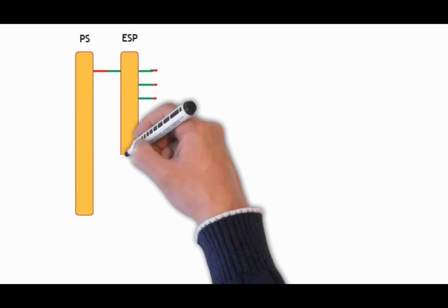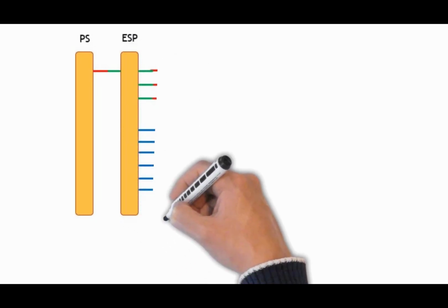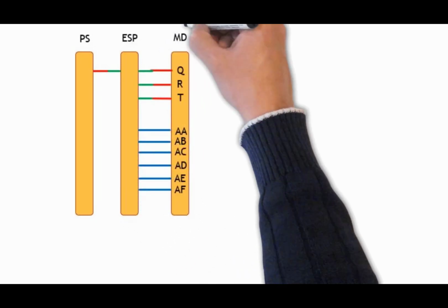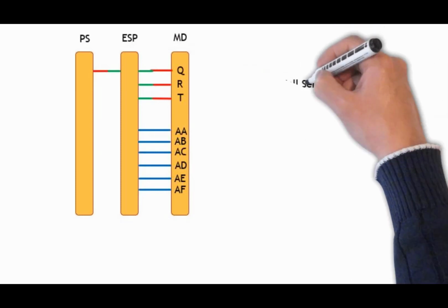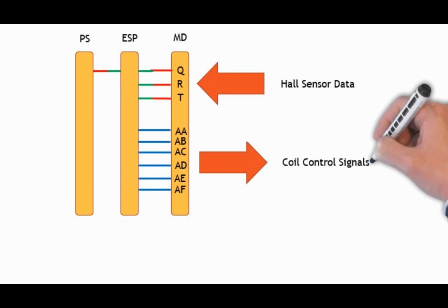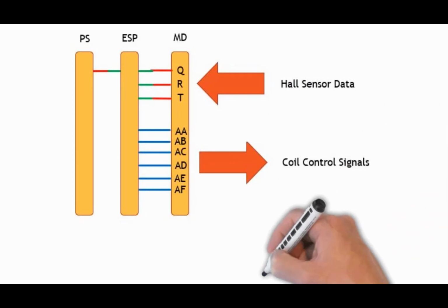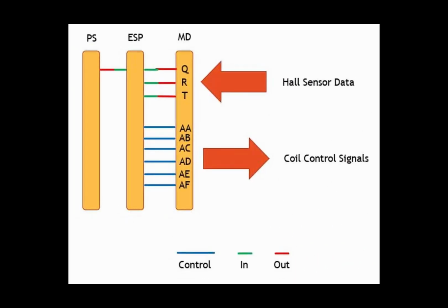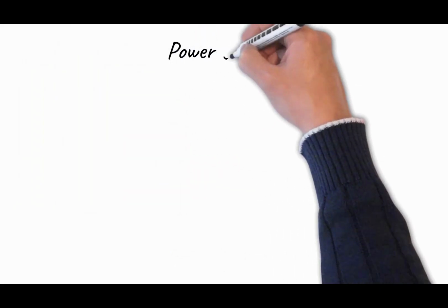From the block diagram, we can see that the processor board receives the data from the Hall effect sensors. After processing the data to calculate the coil that should be excited next, the data is sent to 3 half-bridge networks. The power is then sent to the respective coil and motion is initiated. This process is continuous and goes on in cycles, enabling the rotary motion of the BLDC motor.